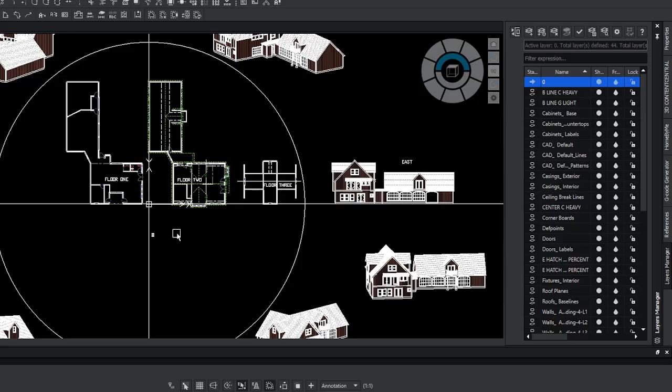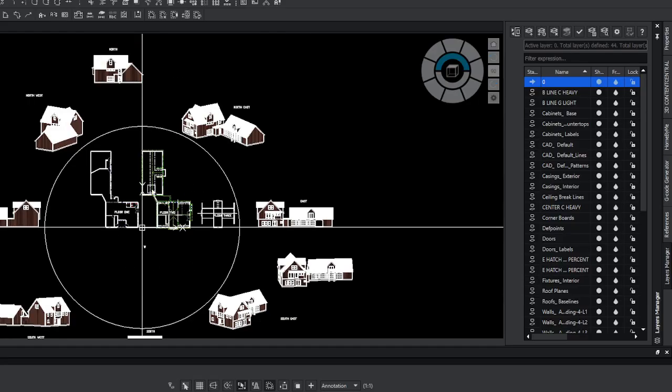So when you're doing a building permit for construction or remodel, you have to do the existing as a complete set of elevations and floor plans, and then you have to do a proposed, which is what you wish to do, what you want to change, what you want to modify, and you do a complete set of the same thing, elevations, plans, and sections based on what you propose.